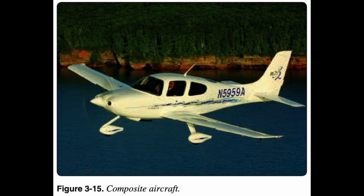This can be greatly improved with a toughened epoxy resin system, as used in the Boeing 787 horizontal and vertical stabilizers. Carbon fiber is more expensive than fiberglass, but the price has dropped due to innovations driven by the B-2 program in the 1980s and Boeing 777 work in the 1990s. Very well-designed carbon fiber structures can be significantly lighter than an equivalent aluminum structure, sometimes by 30% or so.